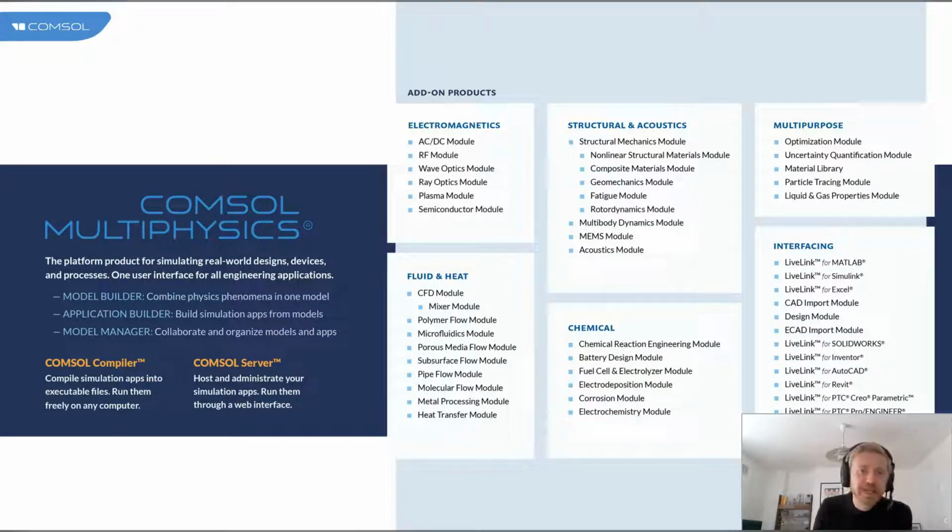In terms of fracture mechanics, yes, you can model fracture mechanics. We have the phase field method implemented that allows you to look at modeling of cracks and crack propagation. What I would add, though, is if you're using this phase field method for propagation, there's a certain amount of smearing that is done across the crack and the crack tip because we're not resolving it nodally. Essentially, it's got the freedom to propagate through mesh elements.